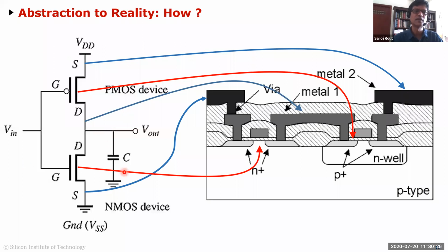So this is how you would connect them in your SPICE simulator or software, whatever you're using to draw it, and then connect it and simulate it and so on. But in reality, this is how it looks in the IC. Okay, this is a cross section of your chip actually. So if you cut your chip right in the middle of those inverters, it's like you have a cake, you cut the cake and you're looking at the layers of the cake, right? So this is like the side view, that's how it looks.